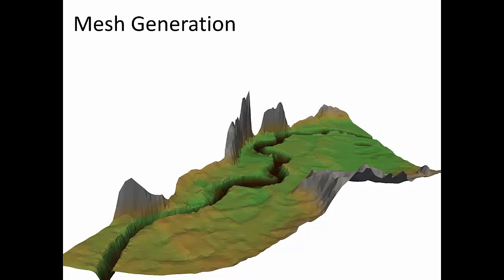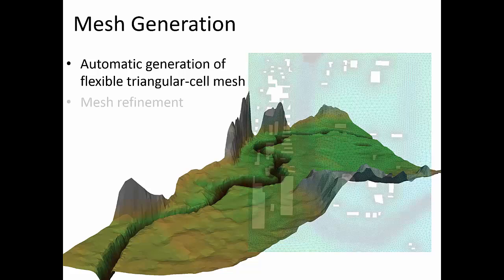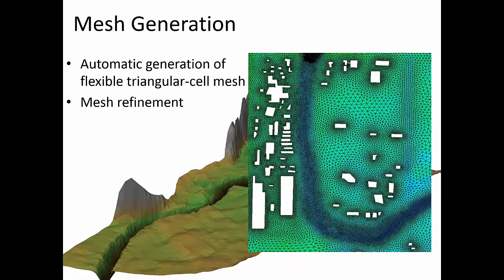And in the full version, you also have tools to generate the mesh, and the mesh can be adapted to any geometry, the main river, the floodplain, even flow around obstacles and so forth. So it's very convenient to adapt to irregular environments as often occur in actual infrastructure assessments.